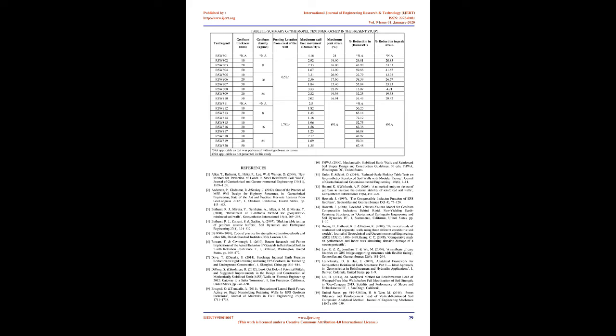At the same time, when footing is placed over the backfill, lateral earth pressure increases on the reinforced soil with settlement of footing. This lateral earth pressure mainly affects the upper half portion of the reinforced soil wall, showing translational outward movements in direct sliding. The geofoam panel placed behind the reinforced zone allows the movements in backfill soil, resulting in shear strength mobilization of the backfill soil. This facilitates the absorption of the deformations due to footing settlements in terms of geofoam compression and reduced lateral earth pressure due to shear strength mobilization.